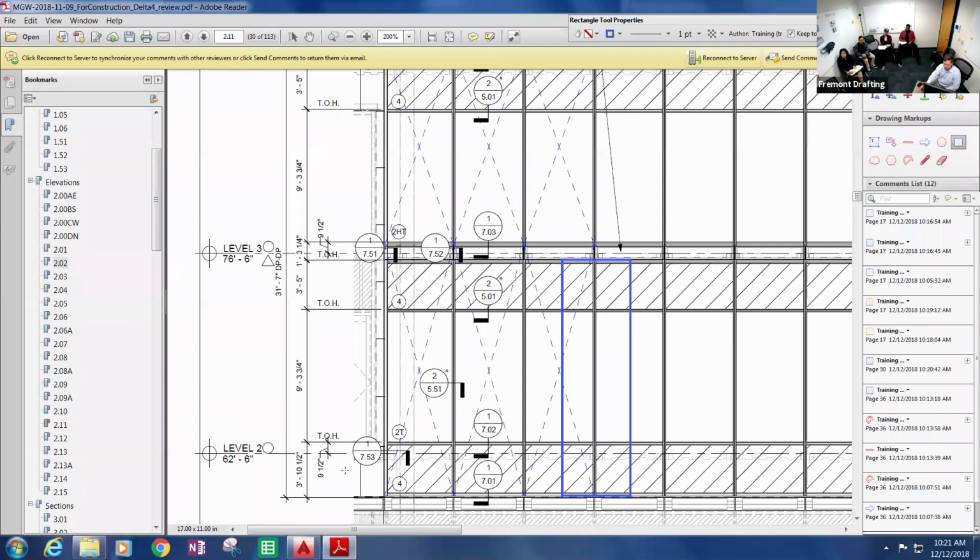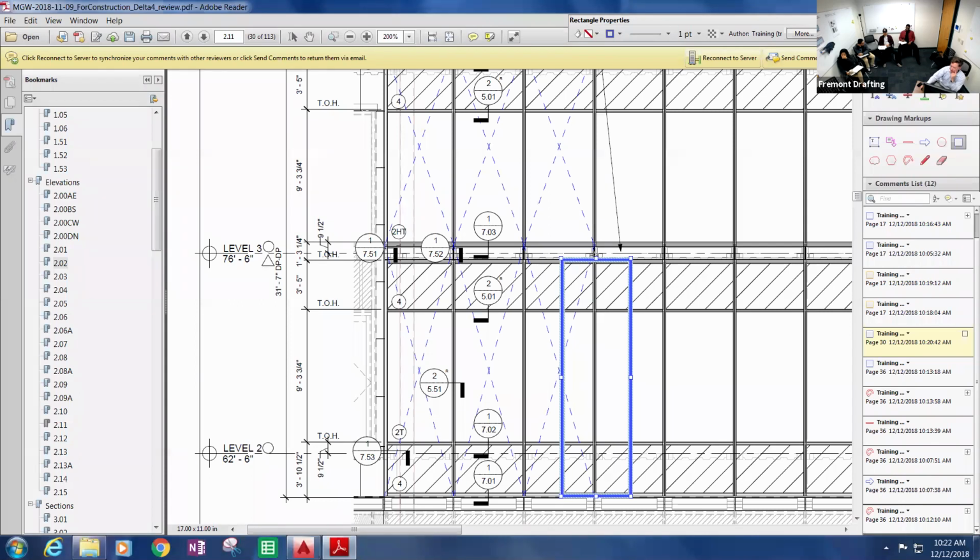So just this end point down here, what it can be. But as I'm counting the deflection, it's not just anchor to anchor, it's actually the entire length of the mullion in this particular case. And then, similar to the stick wall, because we dead load at the top, this is my tributary area for dead load as well. And even though these are 2 separate units, this anchor is taking the right half of this unit and the left half of that unit. And so that's the total amount of area that's the dead load on that anchor.